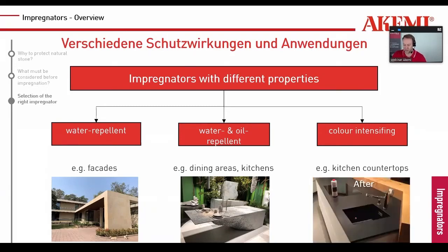I see we have a next question. What kind of impregnator for an internal floor, Italian marble or Indian lime, for example, water-based or solvent-based? Please assume there's some moisture. If there's moisture, of course, we can only go with a water-based product, if the moisture is already in the stone. If it's coming later on, this doesn't matter.